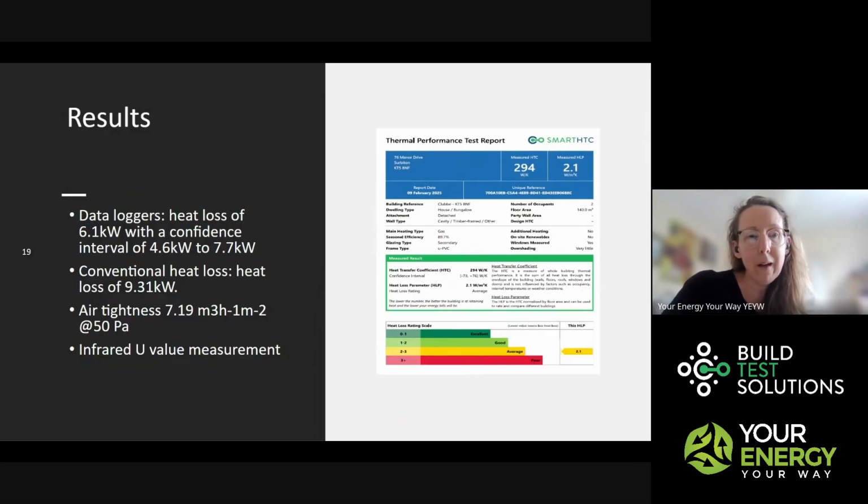Typically, we find that any house that has wet plaster rather than being done with dot and dab tends to come up pretty airtight. That's my observation, not based on many. Well, yeah, based on quite a few measurements. So the next step, given the uncertainty and obviously the risk as a heat pump installer to go in and put in a much too small unit,